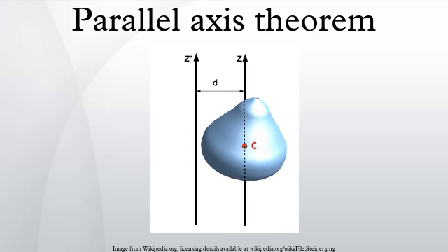For diagonal elements, displacements perpendicular to the axis of rotation result in the above simplified version of the parallel axis theorem. The generalized version of the parallel axis theorem can be expressed in coordinate-free notation, where E3 is the 3×3 identity matrix and ⊗ is the outer product.